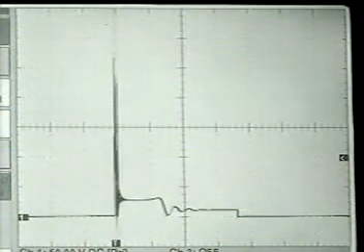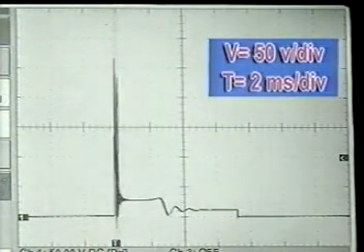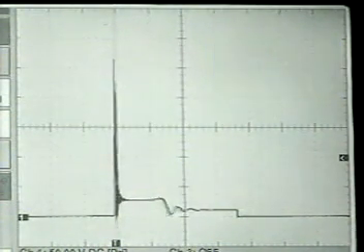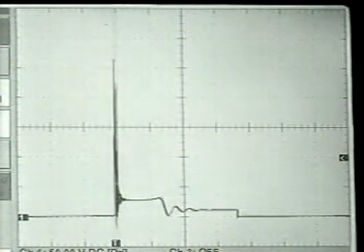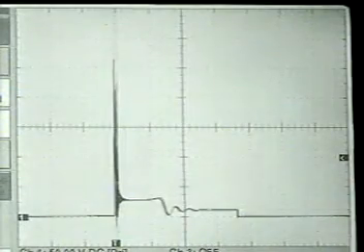Now, looking at this primary waveform, and remember we said measuring the values is critical. You will notice the lab scope is set at 50 volts per division, so you will notice the primary inductive kick is good at about 300 volts. If you focus on the spark duration period, we've got a good, healthy 1.5 millisecond spark duration period. That tells us that the secondary loading effect is good. This misfire cannot be caused by anything in the secondary circuit.